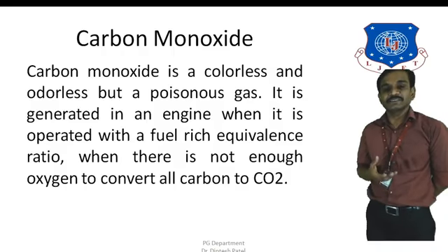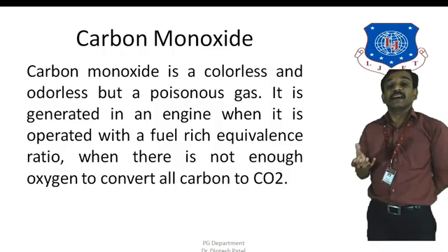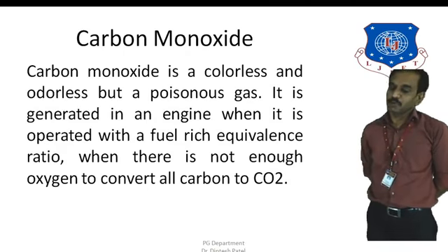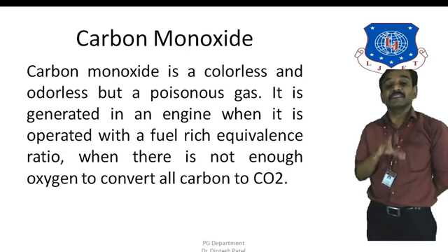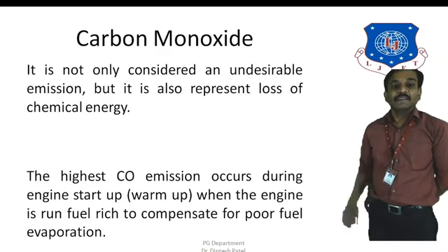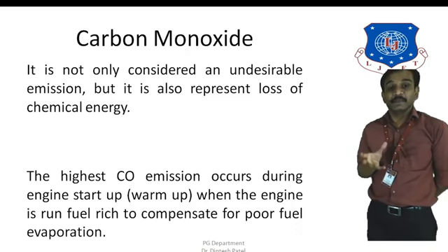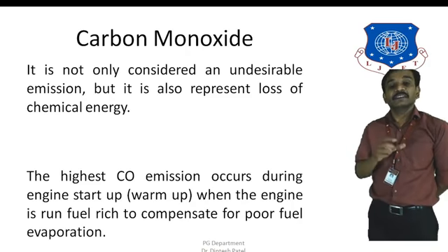At that situation, the rich mixture enters the combustion chamber, and the highest amount of carbon monoxide is produced. Now, carbon monoxide is created because there is not enough oxygen to convert all the carbon into carbon dioxide, and therefore it turns into carbon monoxide. Carbon monoxide is considered an undesirable emission because it creates pollution.